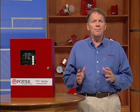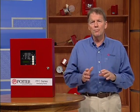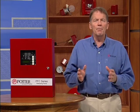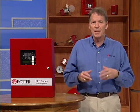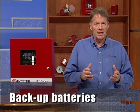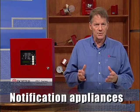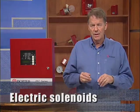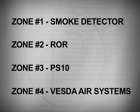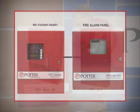The PFC 4410RC releasing panel is the controller for the releasing system. The panel monitors many different pieces that make up the system. These pieces include the panel, backup batteries, various initiating devices, notification appliances, and electric solenoid. The releasing panel monitors initiating devices by area or zone. The releasing panel's relay contacts are in turn monitored by the main fire alarm panel.